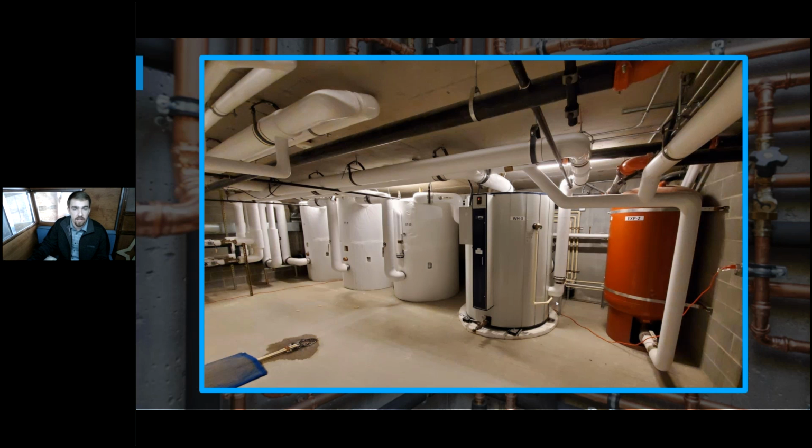And then here we see water heater 3 as it's labeled. This is our temperature maintenance heater that is heating that recirculation loop. And then just out of the screen here is that heat pump that's paired with this heater. So it's serving that mixing valve in parallel. So then that loop can continue to circulate and return back to this tank. And then these tanks remain stratified with that really cold city water coming in the bottom rather than the warm water that would affect those heat pumps differently and potentially mix this storage up.